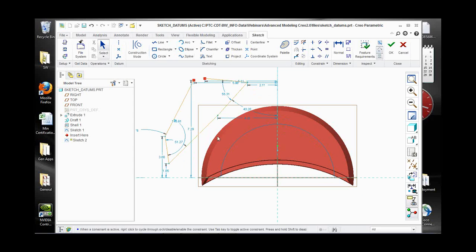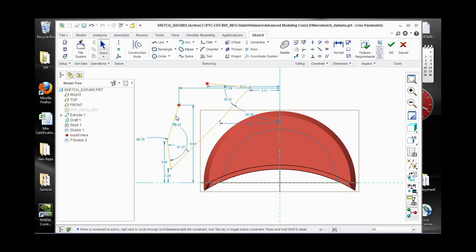But what you can do now, at least in Creo 2, I can't remember if you can do it in 5, is that you can lock entities. Now, the difference is we can go in and pick a dimension and right-click and do a lock, pretty easy. But you also can come in now, pick an entity, right-click, and say, I want to lock that entity. Now, what that does is that it prevents you from manipulating that entity by dragging.